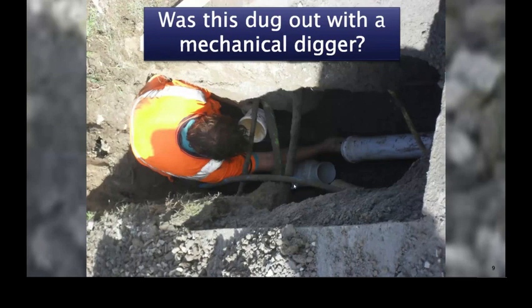And that should have identified where those services are beforehand. Because a digger bucket, the bigger the digger is, you just think you're pulling a tree root or you've hit a rock or whatever. You don't really have that feel to know that you're actually ripping a power cable or something out of the ground. It'll just rip through it.